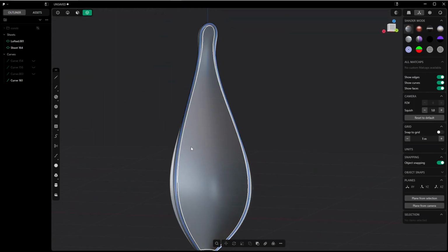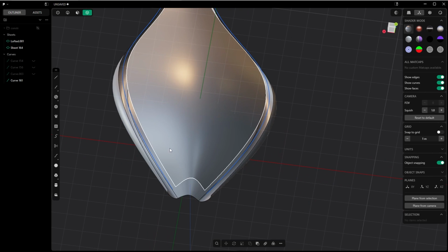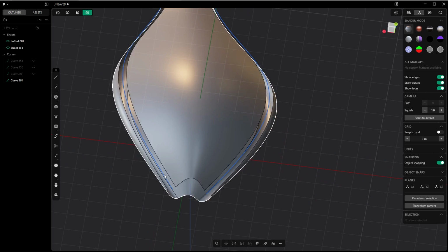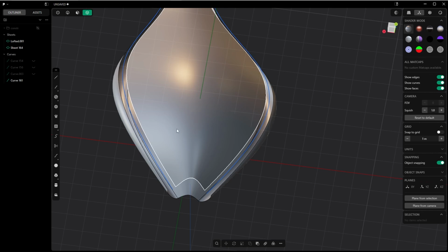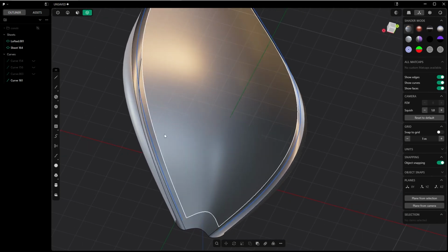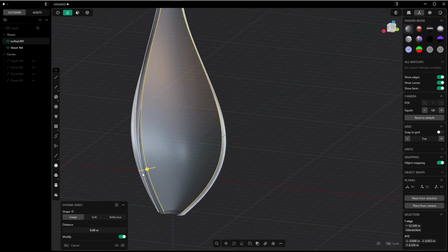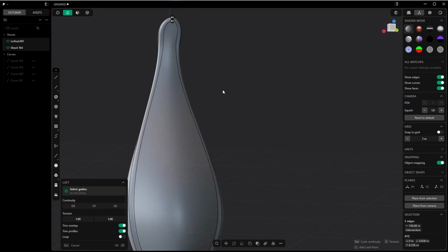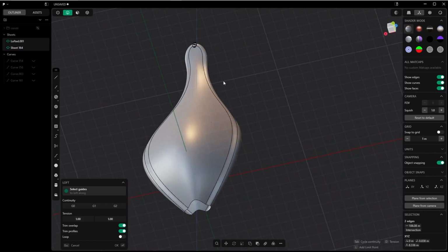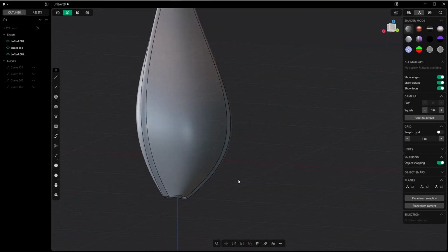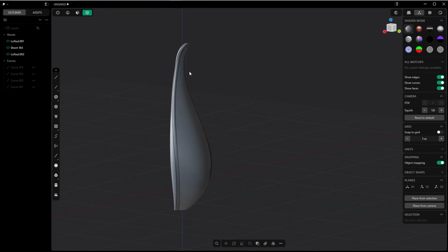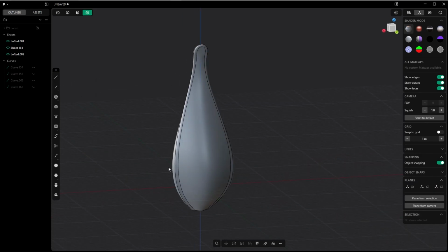But in more complex situations, it's a better idea to convert the solid from which you want to subtract first into a sheet by deleting a small face, and run the difference boolean after you have converted this one into a sheet. I hope it makes sense. It sounds a little bit complicated. And now let's see if we can get away with simply lofting these two edges with G1 continuity, and I think that looks okay. And since this is supposed to be a quick tutorial, I won't make any further adjustments.